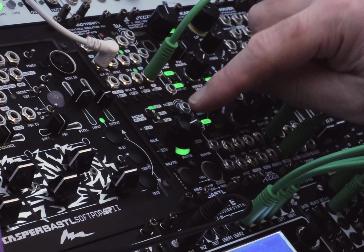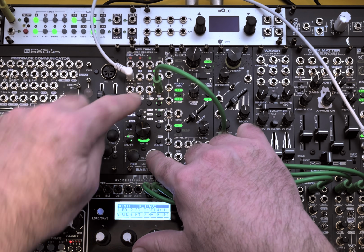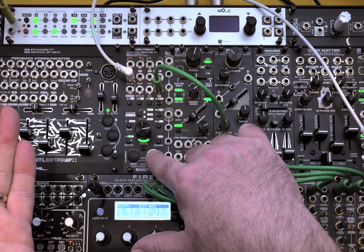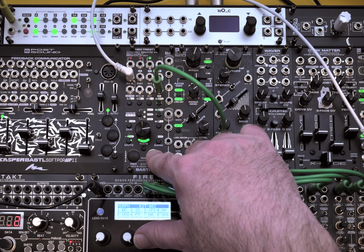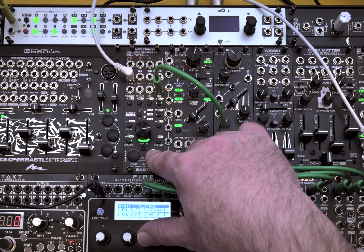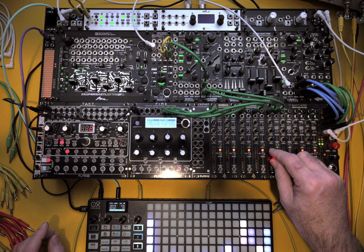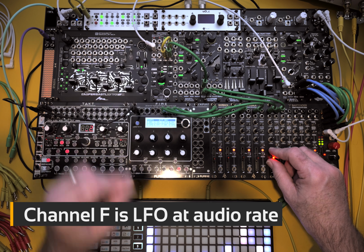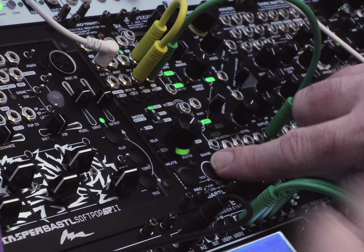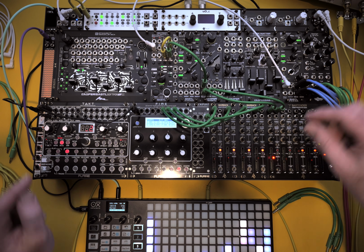We'd like to quantize that, so let's use the quantizer on channel E. We set it to CV mode, which is the mode we're always using for CV processing. And if I press shift, you can see I have D light illuminated, so the quantizer is on, and A, B, and C are off because I'm in the minor scale. Now voltages on the E channel are quantized into the minor scale, so we can patch that into input F. All right, we're getting somewhere now. We listen. We could go into channel E and adjust the frequency of the oscillator. And of course, I can change the wave shape. That's a ramp down. There's triangle. There's pulse. I'll leave it on ramp down for now.